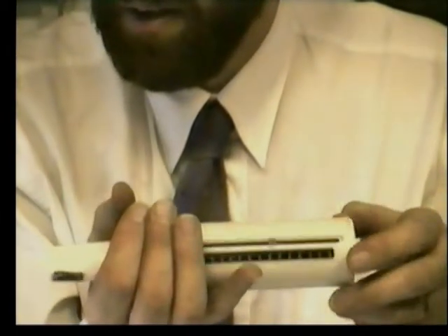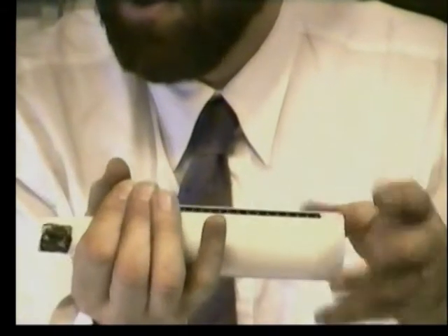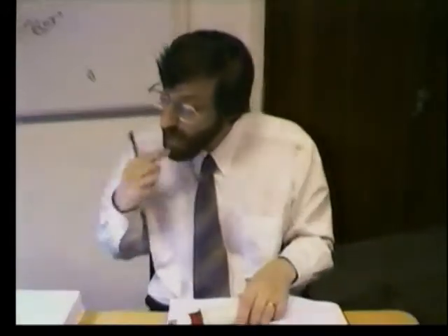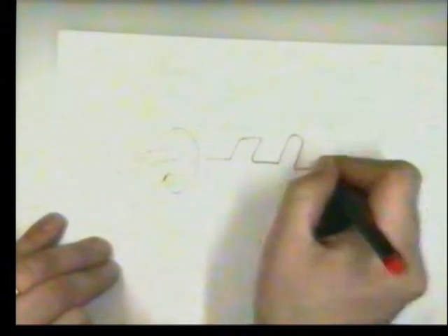So here's 0, 1 rotation, 2 rotations, 3 rotations. Very simple. The rotating shaft will give us a pulse train that we can take directly into an I/O pin of our processor, and if we've got a pointer in our program that accesses that memory location, we can just count the transitions from 0 to 1 and then from 1 to 0, and that tells us how many times it's rotated.